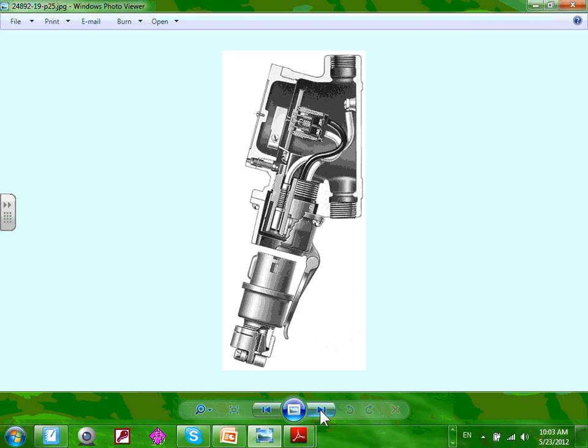So that's my starter. Here's how they do the plug-in. We're talking about the receptacle. This is an explosion-proof receptacle. Believe it or not, the room that you guys specified in a class 1 div 1 location, we did 2 receptacles per wall for a total of 8 receptacles. These receptacles must be like this. So on your plan, you should have specified that your receptacle has to be class 1 div 1.